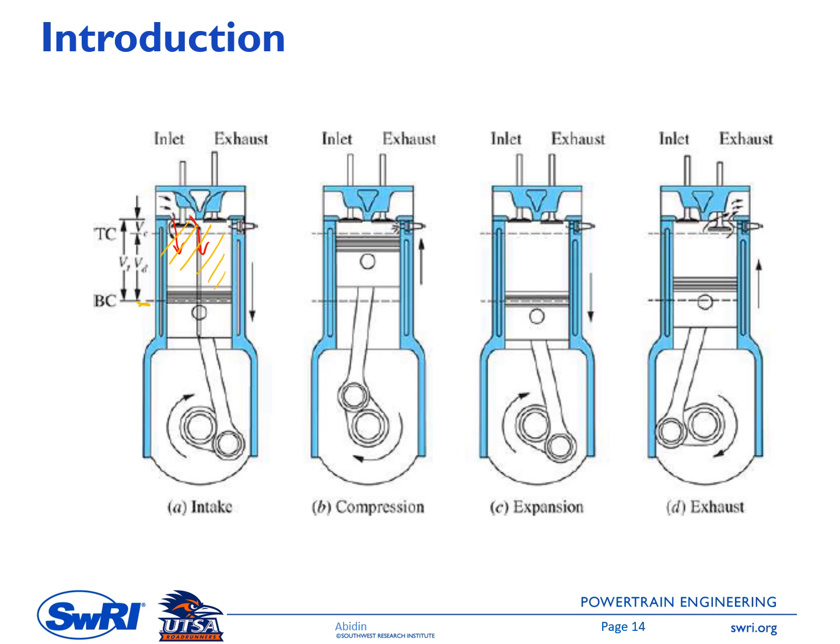And then the piston moves up again, compressing the mixture inside the combustion chamber. So you see the piston move up, and then the cylinder volume, the combustion chamber volume, decreases, and you can see also the intake valve closed there, and we have a combustion process there, increasing pressure and temperature, and then the piston moves down again toward BDC. So we have an expansion process or expansion stroke, also called power stroke here. Okay, so this one.